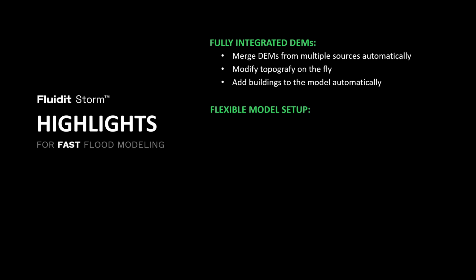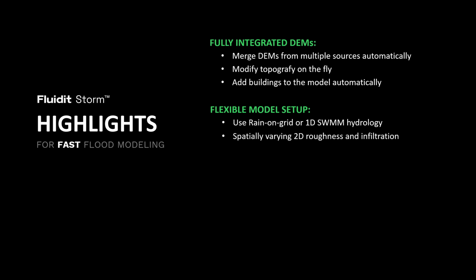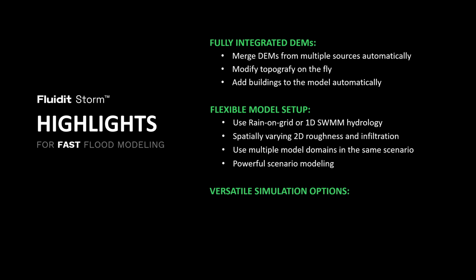You can use a rain on the grid approach or SWMM hydrology, and even both in some cases. Spatially varying parameters, multiple flood model domains at once, model different scenarios, compare them, and even use statistical analysis for the results, and finally the versatile options discussed in this video.